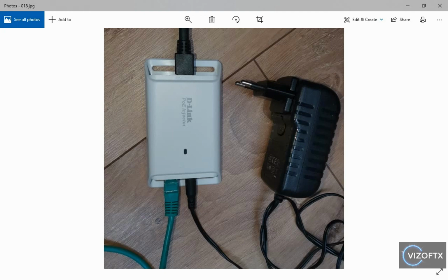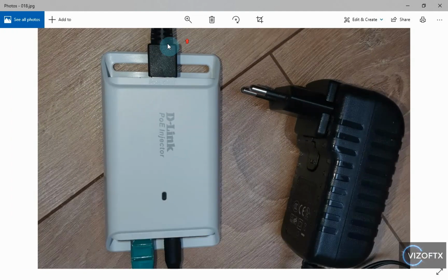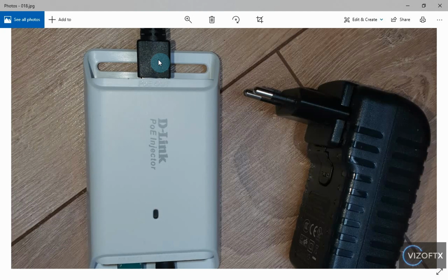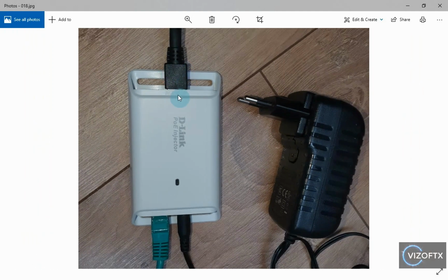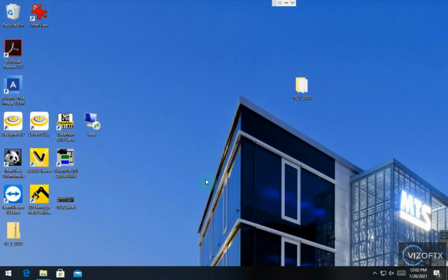As I mentioned, the camera has a standard Ethernet port, and if you need to connect, for example, to a laptop or computer which does not support PoE and you do not have a PoE switch, or a suitable power I/O cable and power supply for it, you can also use a PoE injector, to which you connect a cable that goes to the computer into one of the holes. Connect the cable that goes to the camera on the other side. And that cable is powered by this AC adapter. There is PoE out. Well, I chatted a little.